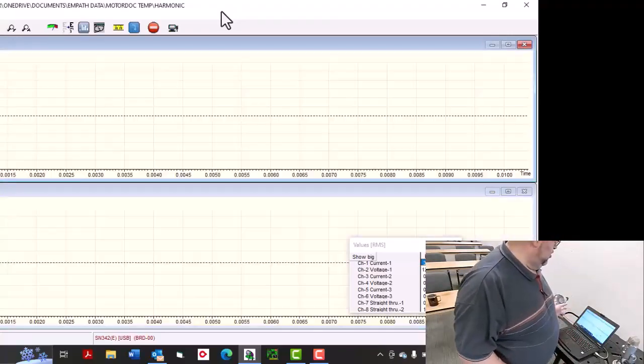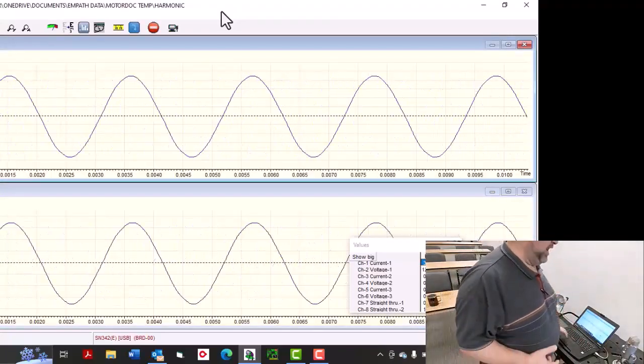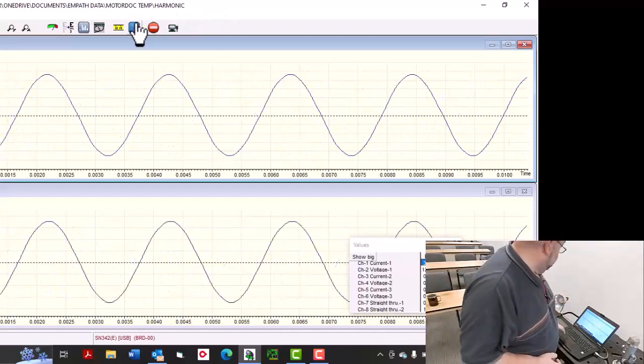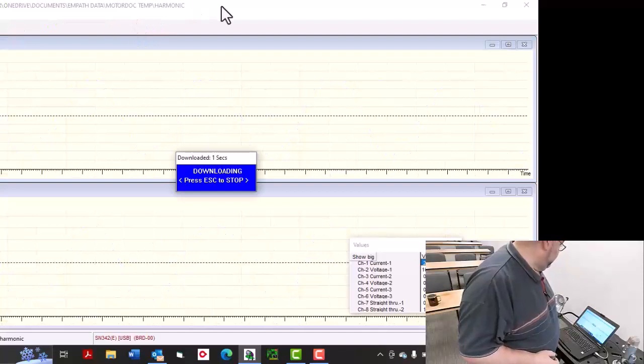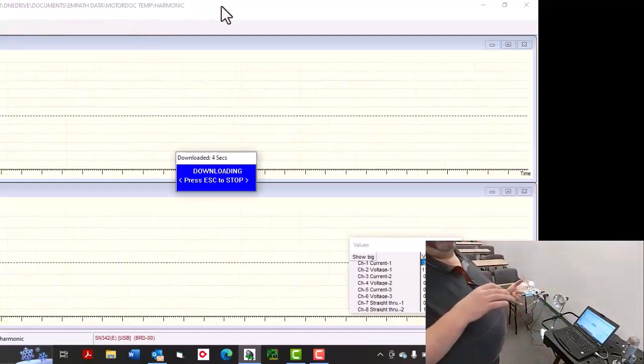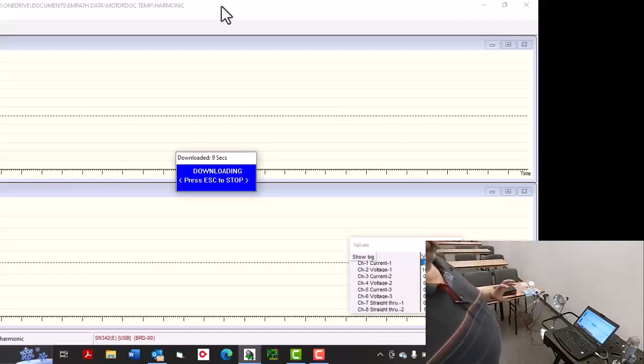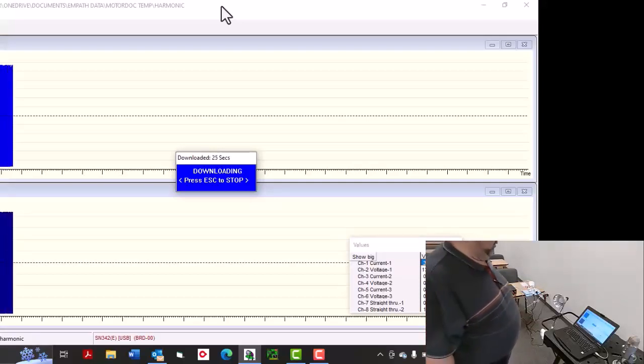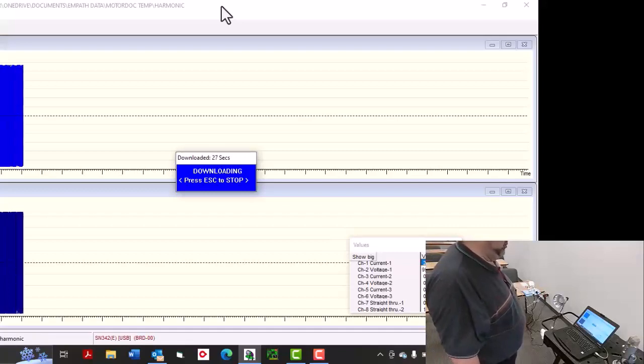So the linear load is not having a significant impact on power factor. It should actually be 1 if I was in a perfect system. I'm just into an outlet. Now on that outlet, I have some of our servers and some other stuff, and that's all feeding a little bit. That's that teeny little bit in there, plus our air conditioning systems all come off the same system. Now, unlike my old facility, I don't have 277/480 here. It's 120/240.